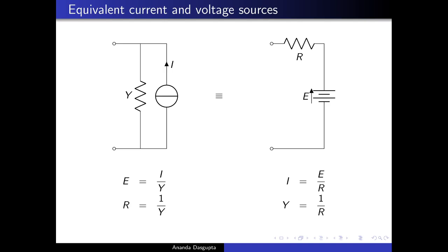Actually, when a battery runs out, in the language that we use in daily life, what has happened is chemical processes inside the battery end up increasing its internal resistance a lot. So it hardly manages to deliver any current. But a good battery has a very small internal resistance. A good current source, on the other hand, should have a very small internal admittance, so that very little current is diverted through that branch.